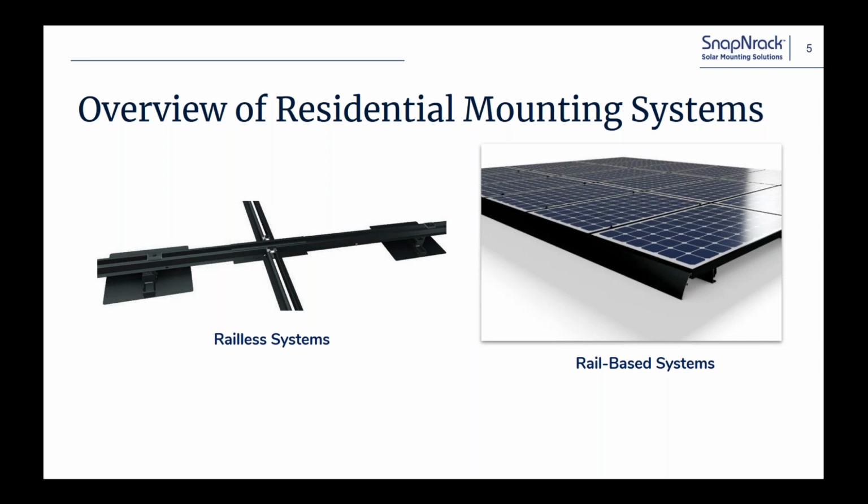It goes directly from the attachment point to the module. With rail-based systems, you have an attachment point, then the rail, and then the modules, and the rail is more of an interface between the attachment point and the module itself. That's basically because there is no attachment point right where you need it, so you've got to get to a rafter or something to attach your system to.